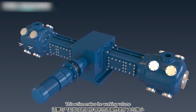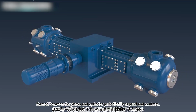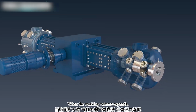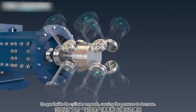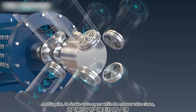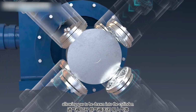This action makes the working volume formed between the piston and the cylinder periodically expand and contract. When the working volume expands, the gas inside the cylinder expands, causing the pressure to decrease. At this point, the intake valve opens while the exhaust valve closes, allowing gas to be drawn into the cylinder.